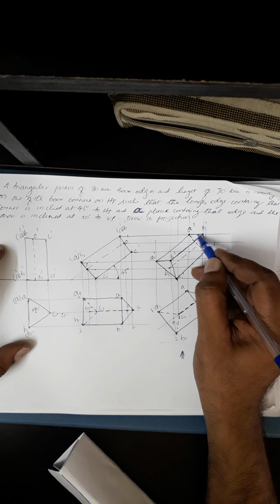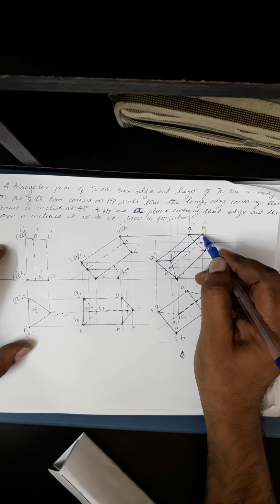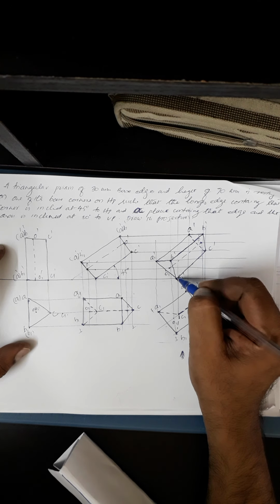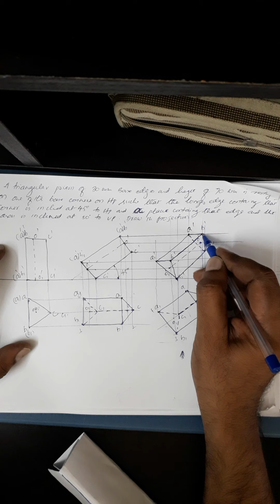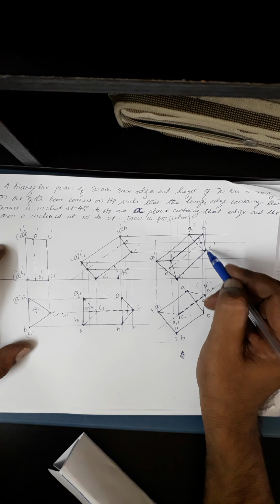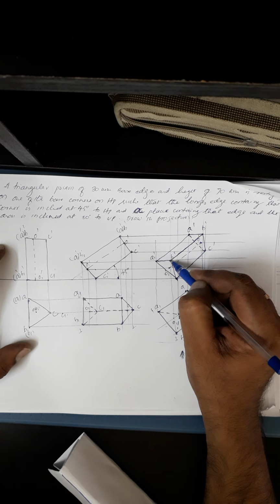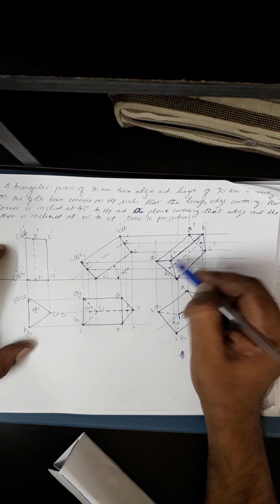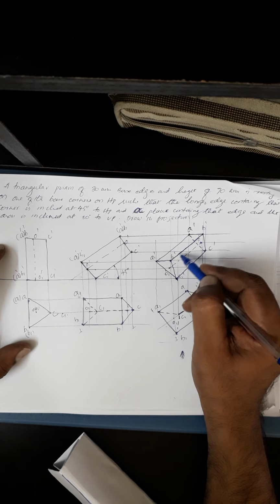Then you go for the outermost edges. All outermost edges are visible. So complete all of them with a thick continuous line. Then this is B1, and B is the end point of this B1. So if you can see, B1 is the outermost point on the outermost boundary, and this is the visible end face where the other point is visible. If we can see both the end points of a line, the complete length is visible. That way you can make this line a thick continuous line.